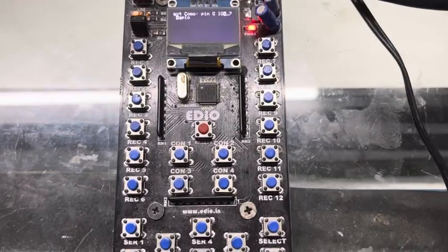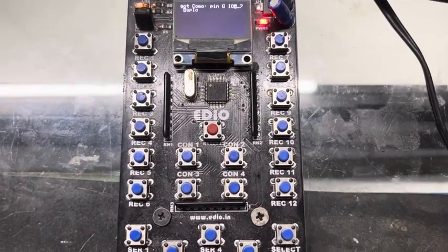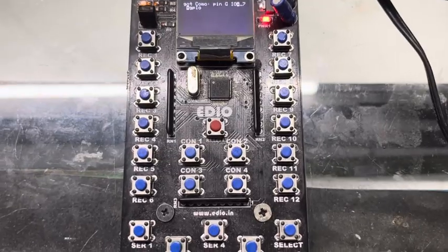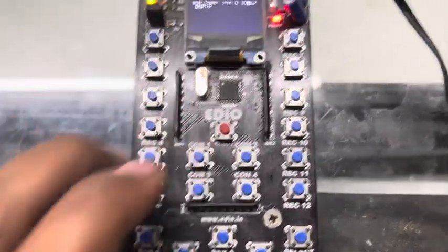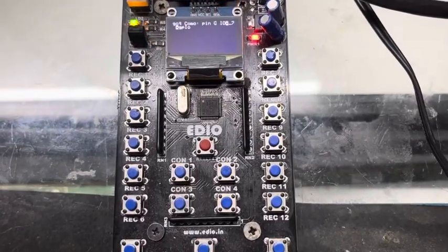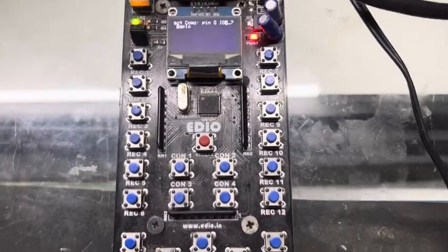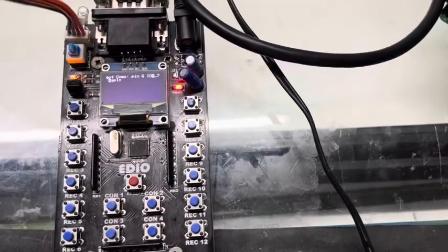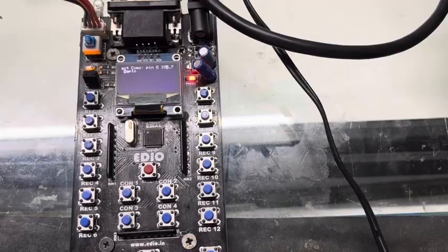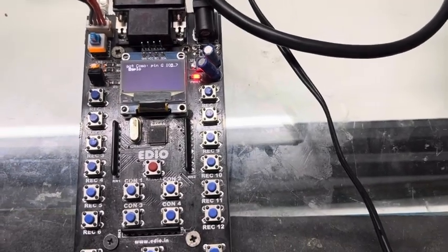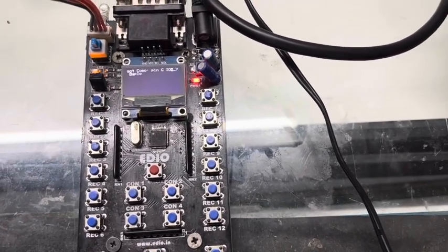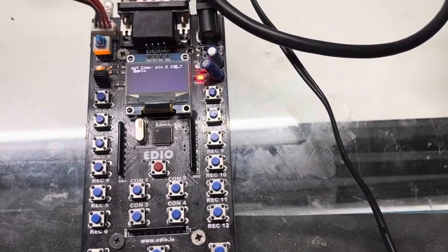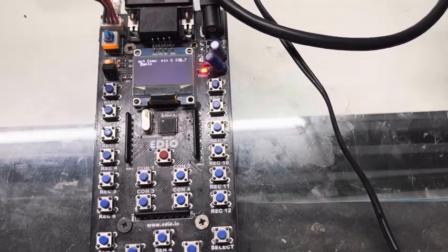So for example, if you want to enter into the M-Star motherboard's console mode, you have to power off your motherboard and then just press the console on button. You switch on your motherboard, you will get the proper data. It automatically enters into console mode. But the same thing, if you use this MI motherboard, sorry, an AMLogic processor, it won't work, because based on the processor, the console entering function will change. For M-Star, MediaTek, some motherboards, if you want to enter into the console mode, you have to power off your programmer, power on your motherboard.